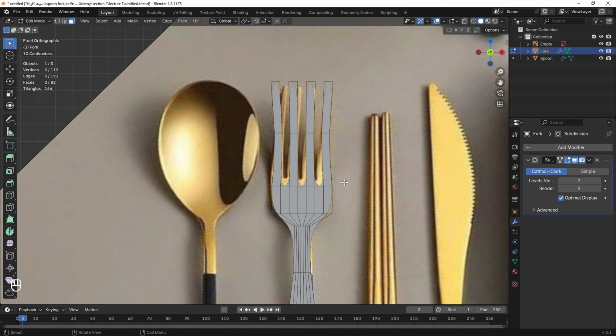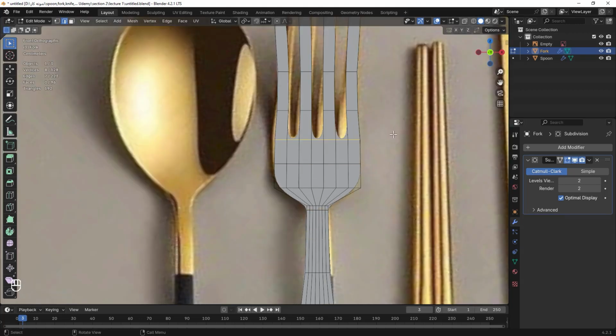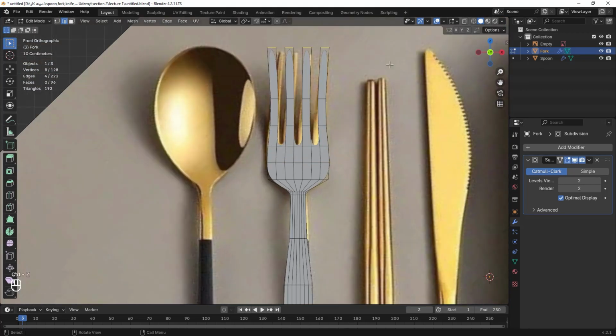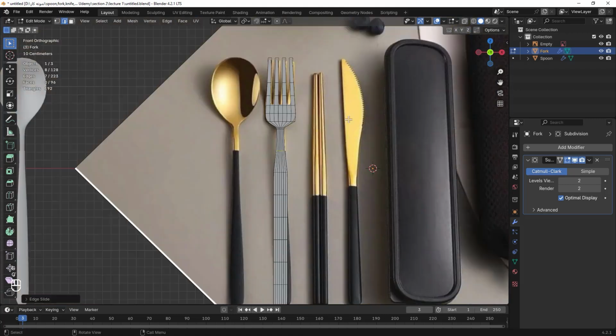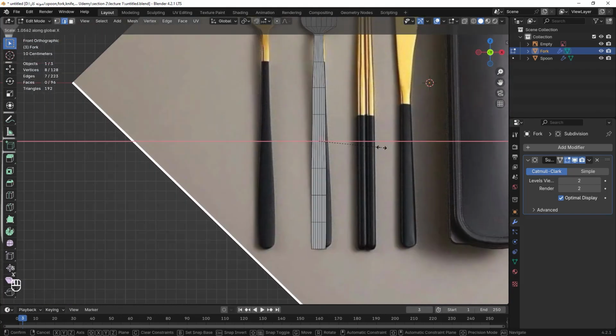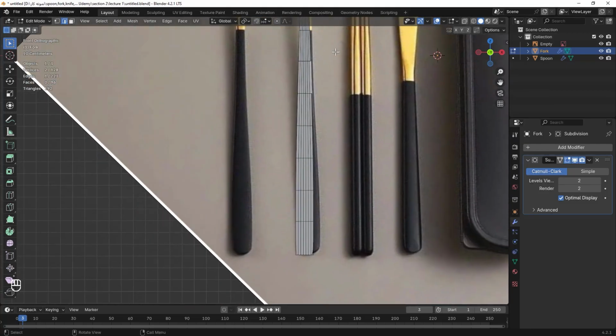We try to get the best result by using changes in the lines. I put some of the video on higher speed, so we adjust all the lines and points in the X direction with scaling, add more loop cuts if needed, and also in the Z direction by pressing G twice, as best as possible.